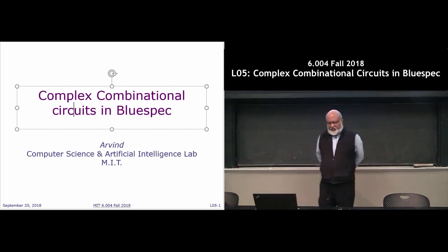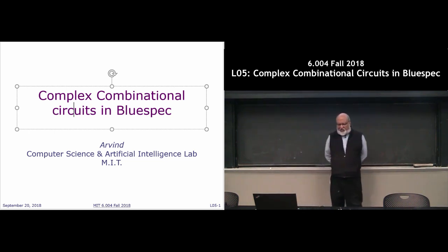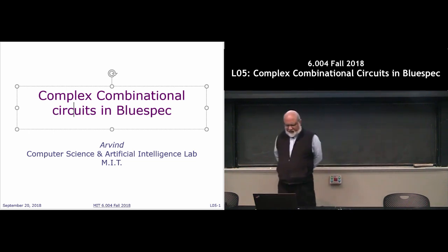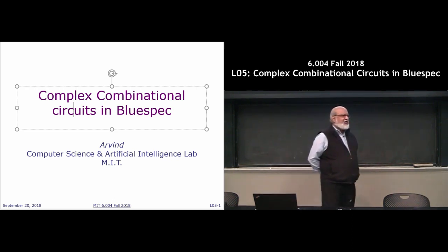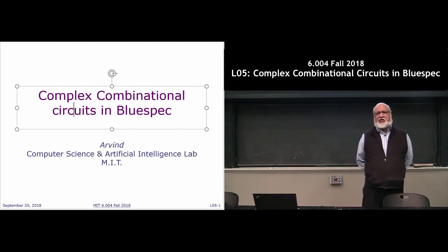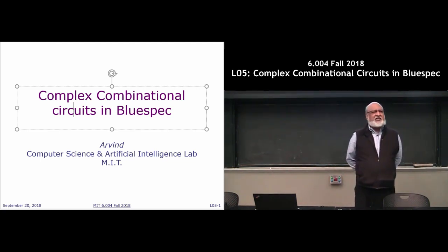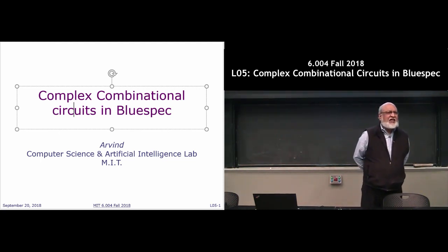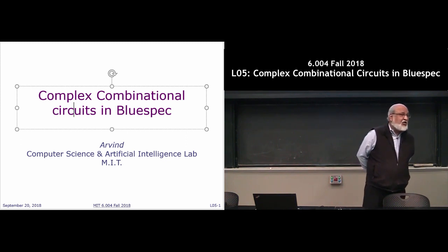Okay, the Bluespec compiler automatically assigns a bit representation to the three colors. So the question comes up, why is this better? Why is this style of coding better than you yourself coding and saying red is 0, 0? Anybody? Yes? It abstracts the encoding. Right.